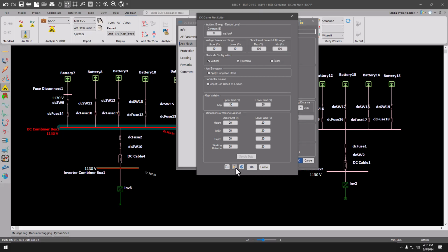radial feed, right? Now, when using C areas for locations with multiple sources, we do need to make some adjustments in order to factor in that difference, because, of course, we want to make sure that we use these curves appropriately. So the way we can do this here is to target the amount of incident energy that each of these sources should deliver in order for us to get a combined incident energy of 8 calories in this particular example.